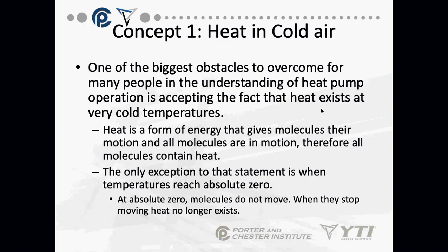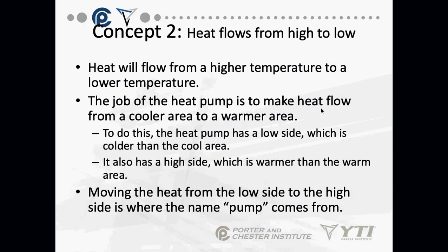One of the biggest obstacles for most people in understanding a heat pump is to accept that heat exists at very cold temperatures. Okay? We have heat outside at all times until you reach absolute zero. Now, usable heat is at a slightly higher temperature, but there's heat outside at all times. Heat will flow from a high temperature to a low temperature. The job of this heat pump is to make heat flow from a cooler area to a warmer area.